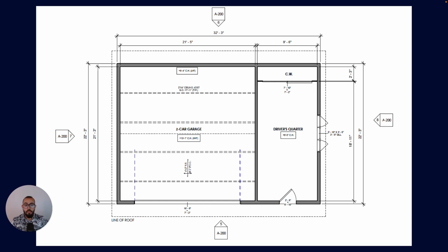This one is one of many types of as-built drawings. This is a floor plan view specifically. A floor plan represents a bird's eye view of a building. And here, like I mentioned earlier, this is a 2D layout of this garage. The most important information that we showcase here is that you will see in the gray the walls.